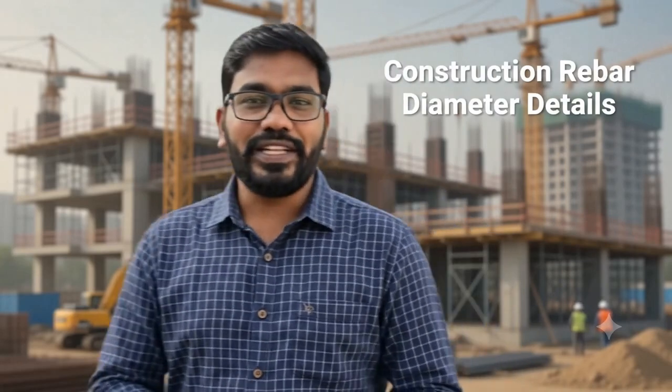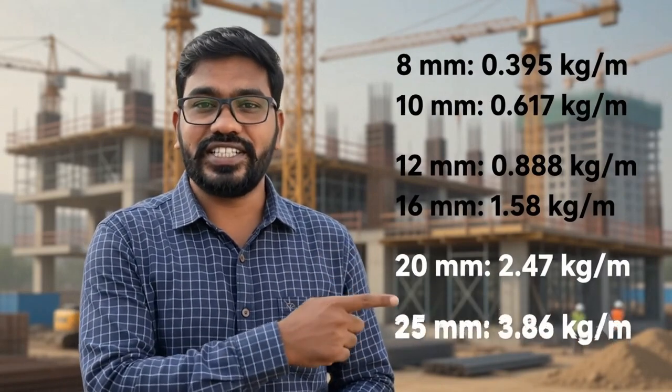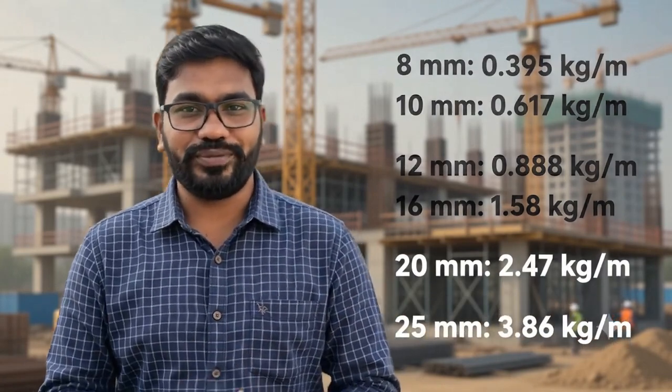To calculate steel quantities, we use the standard formula d squared divided by 162, where d represents the diameter of the reinforcement bar in millimeters. Let's explain construction rebar diameter details. For 8 and 10 millimeters, then 12 and 16, finally 20 and 25.